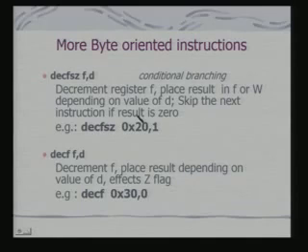This is a very interesting feature. Another interesting thing that happens is that when this result is 0, the PIC has to skip the next instruction. And if you remember the way the PIC instructions are executed, I told you in the last class that while an instruction is being executed, the next instruction is fetched. Now in this case what happens?